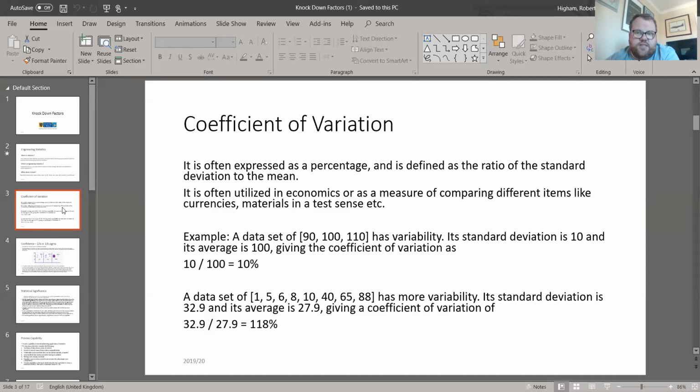So if we have a standard deviation calculation of that, you can't really compare the deviation of ultimate tensile strength with elongation. What the coefficient of variation does is allow us to compare the ratio of those two numbers. So the ratio of a very high number, like ultimate tensile strength, is comparable to the ratio of a very low number. And it's really useful to be able to compare variation in things which are not normally comparable. So you can't compare the standard deviation of ultimate tensile strength with elongation, but you can compare the coefficient of variation. That's the crux of how we use it.